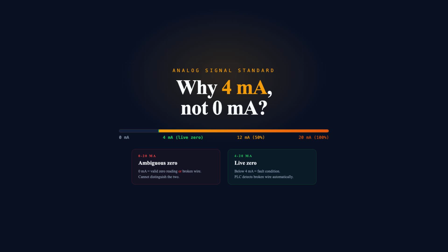A loop carrying 4 milliamps at zero process value is alive. Current is flowing. The transmitter is powered. The wiring is intact. If that current ever drops below 4 milliamps, something is wrong: broken wire, open circuit, unpowered transmitter.